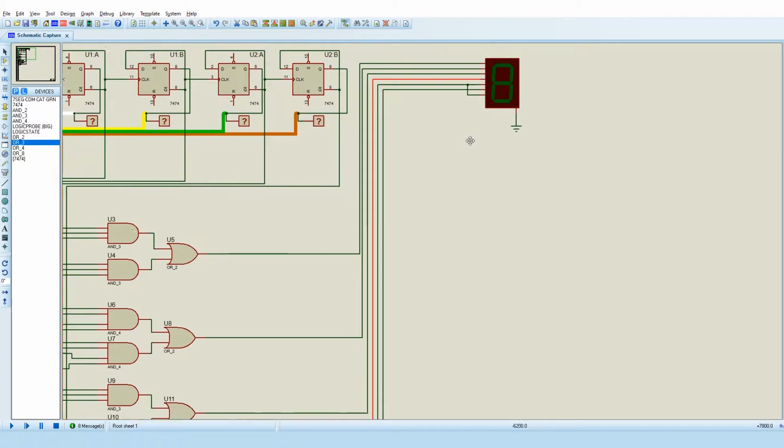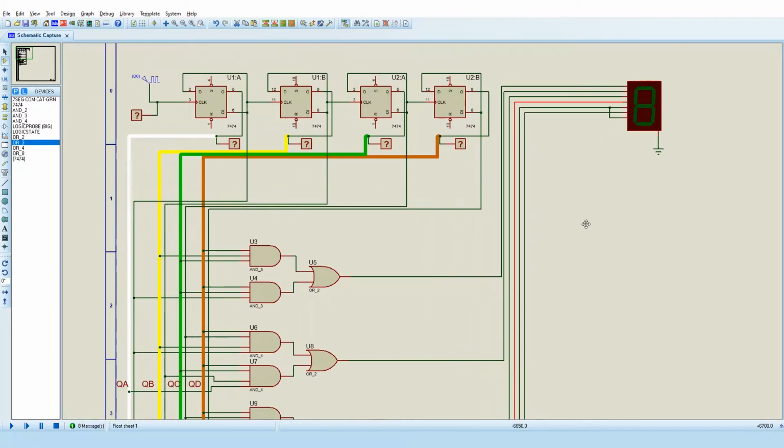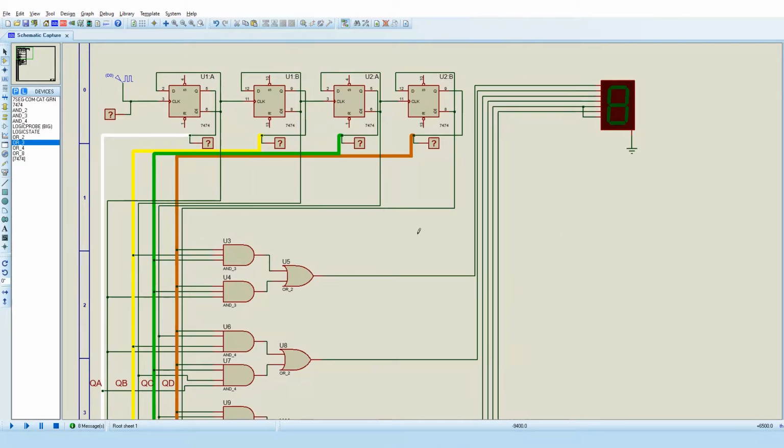We'll identify that shortly if there's a problem with segment A. So we'll simulate it again and see what it looks like now. 1, 2, 3, 4, 5, 6, 7, 8, 9. A isn't quite right still. So where it says A, segment A is missing, and where it should say C, there's an extra segment. That's A, which is worth 10. So the top segment A should be lit and it's off. So we know there's something wrong with it.